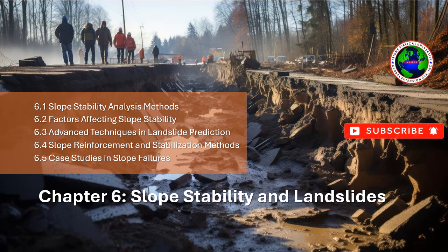6.1.5 Numerical slope stability methods. In addition to the methods mentioned above, several other numerical techniques are commonly used to evaluate slope stability. These include the boundary element method, BEM. This method focuses on solving boundary value problems and is particularly useful for analyzing slopes with complex geometries or irregular boundaries.